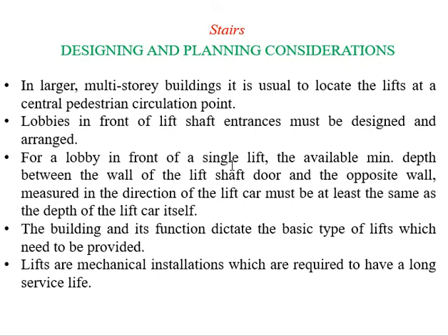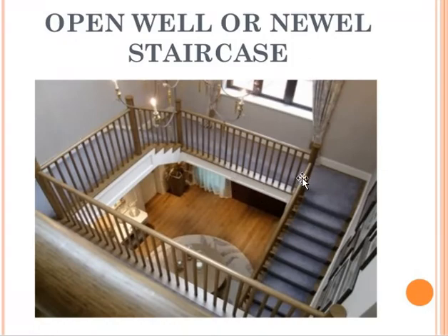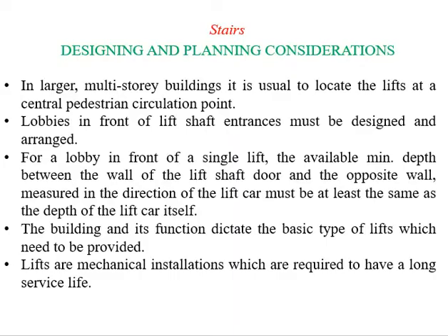If you want to construct a certain type of stair, what are the planning and the designing that goes behind the scene of construction of any type of stair. So if we are in a large and multi-story building, it is usual to locate the lifts at a central pedestrian circulation point. Let's say, if we have drawn this type of staircase, this is the open space, so we can have a lift at this space. So this point is trying to say that we can have a lift at that point if it requires. Next, if there are lobbies in front of the lift shaft entrance, that must be designed and arranged.